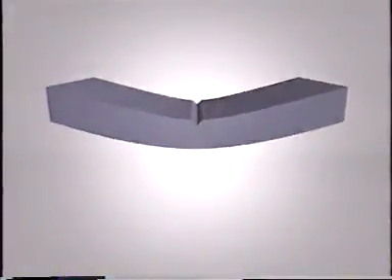If the same load is applied to the beam in both directions, the two fatigue cracks should be symmetrical. The size of the final fracture zone indicates the relative loading of the beam. The fatigue cracks formed under fluctuating load and those formed under reversed load differ in one significant way.